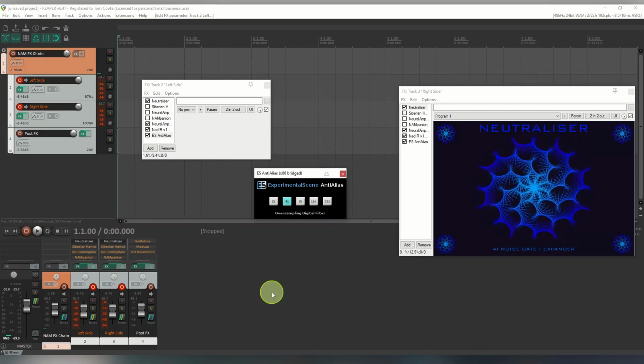So rather than stopping any aliasing happening in the first instance, it oversamples afterwards. It works out what the Nyquist frequency is, which is the frequency at which the sample rate can't reliably handle the information anymore and can start to create aliasing, which could be in the form of just hissing noises, glitchy noises, things you don't want.